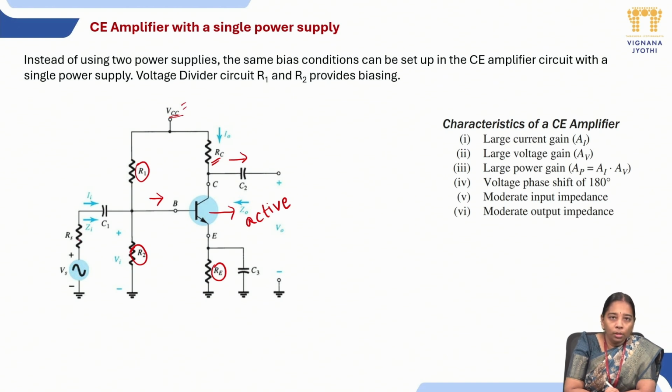It is applied through a source resistance and we are using coupling capacitors C1 and C2. We use C1 and C2 as coupling capacitors because we have the input signal here and also the DC signal here. These two signals might get mixed up, and we would have an input that is a mixture of AC as well as DC.